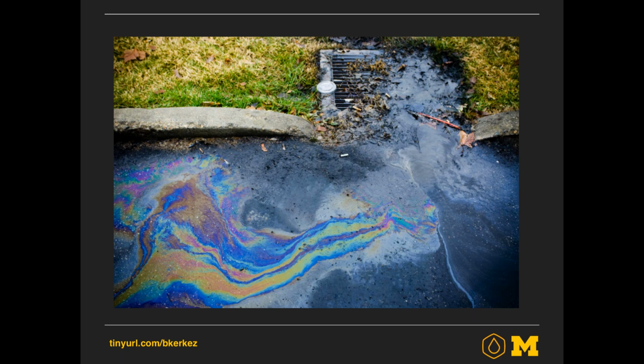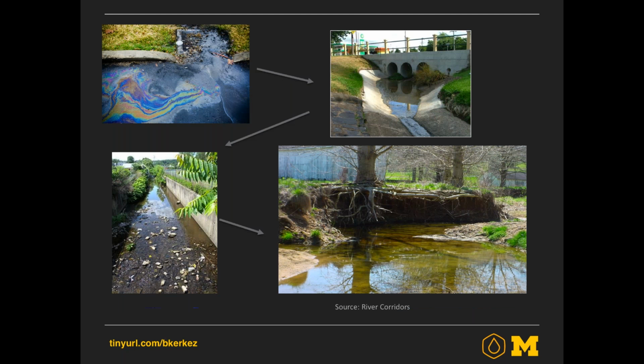And when they leave your neighborhood and go down into these systems that start at potentially a small pipe that becomes a bigger pipe that becomes a bigger concrete culvert, water naturally moves through these systems and can start wreaking havoc in a lot of places. Urban stream syndrome is something that gets brought up commonly as one of the impairments of urban water systems, but it's this idea that we're eroding these natural stream systems that weren't traditionally subjected to these flashy flows.